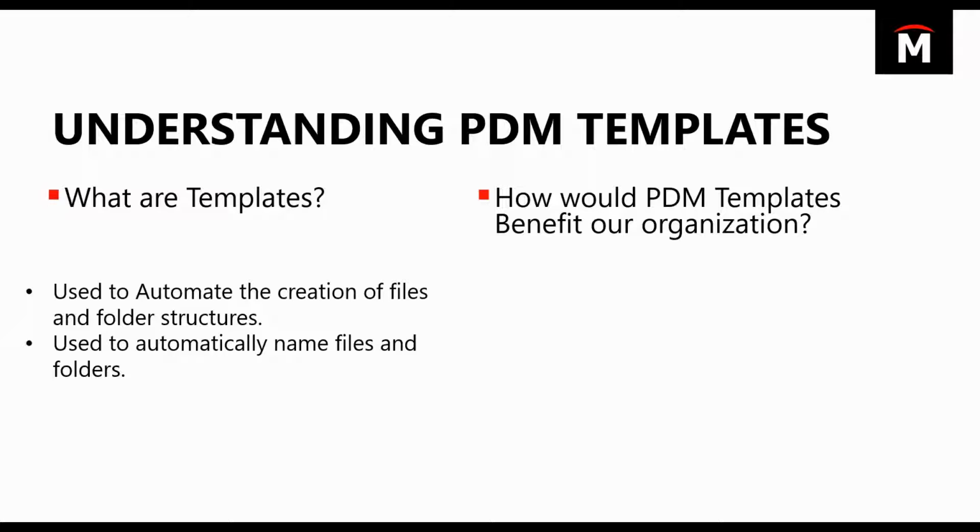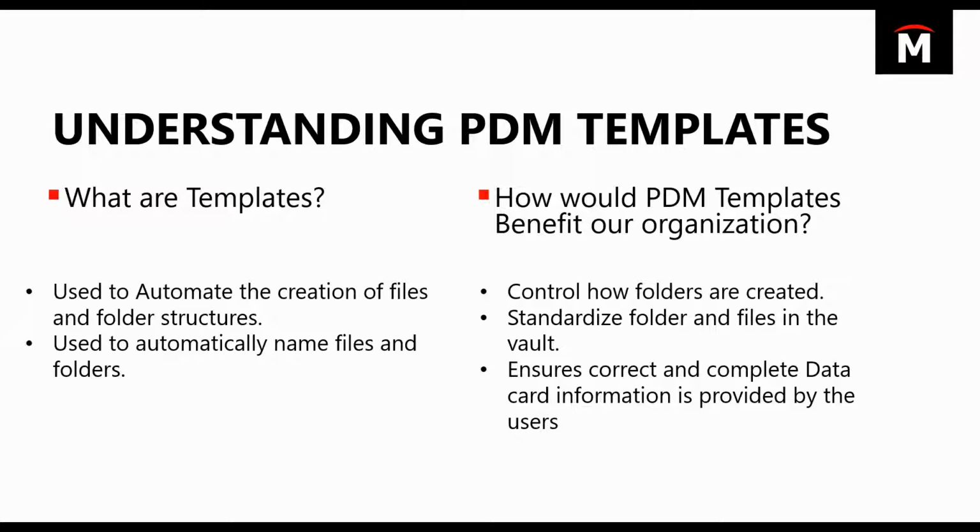Now, how would you benefit from using templates? How would your organization benefit from using templates? Well, the nice thing about the templates is they can control how or where folders and files are created. So, for example, if you had restrictive permissions, so users can't just create folders and files anywhere in the vault, you could override those permissions in the template permissions. So, for example, I couldn't create a folder in a project folder. However, I could run a template that allows me to create the folder. So it gives me another level of permissions, so to speak.